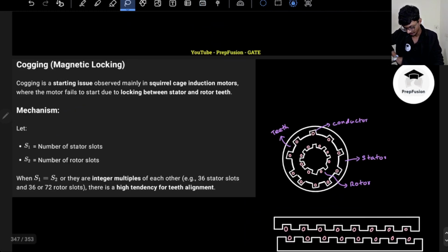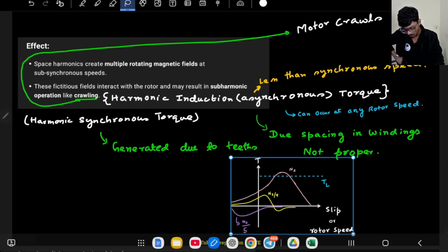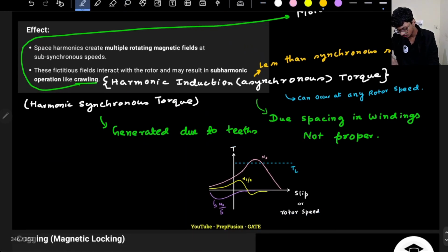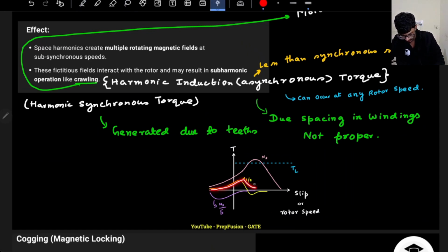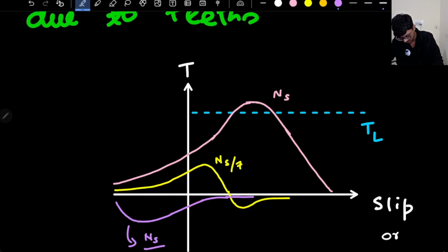So what will happen in reality? Let me show you the overall resultant torque developed. Here it is somewhat positive, here it is negative. The negative is lower and the positive is higher, so initially the torque will increase somewhat. Then I see a sharp decline. This negative part is still constant, so the torque will reduce and cross the initial point. I'm just adding the three graphs, that's it.